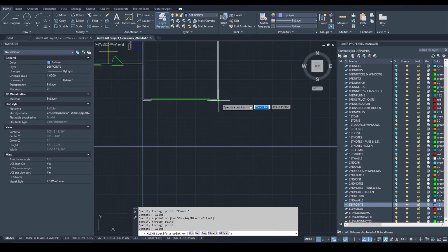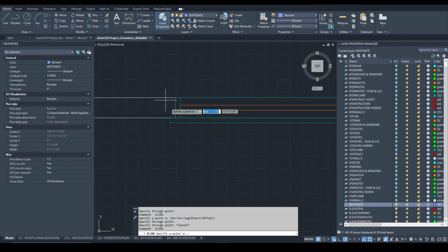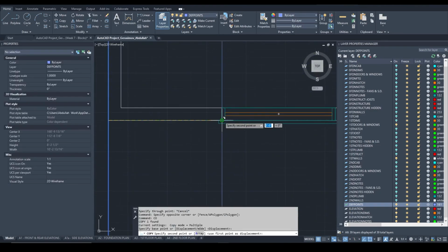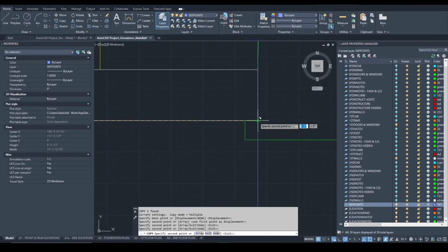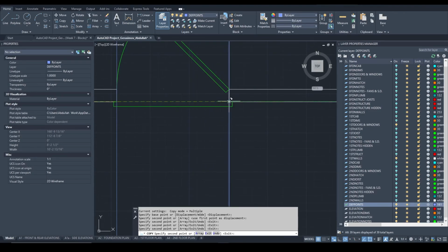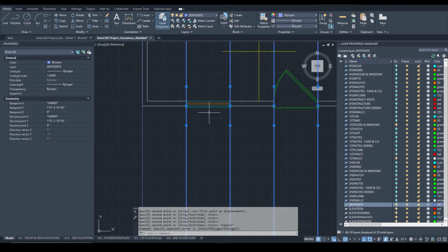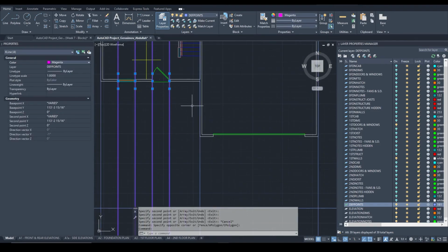Make sure you draw them completely vertically, and the way you can do this is by seeing the green dashed lines. Also, let's copy the XL lines and put them in the openings area, the same way we have done the dimensions. And once you do that, let's change the color of those, but only the color, to magenta. And do the same thing for the garage door opening.